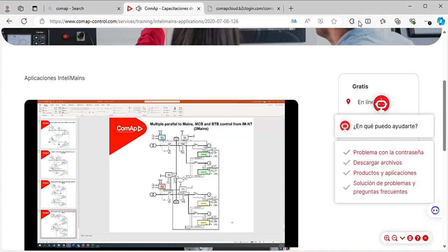And now it is currently operating in manual mode. So if I want to manually operate the whole site and I want to trip the grid and see how I start and stop everything. If I fail the grid here, the MCB will open up on my utility end. That means there is no load, nothing, and I have to go and press my MCB manually because it is in manual mode, but my gensets won't start here because there is no auto mode operation given to the controllers. So I have to manually go and start my genset, which is pre-starting, similarly I will start my second genset, which is also starting.